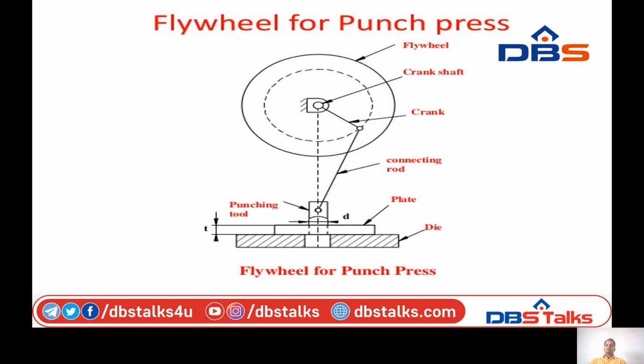We know the function of a flywheel, or its application in an engine, is to reduce the fluctuation of speed. When the load on the crankshaft is maintained constant and the input torque varies during the cycle, the flywheel can also be used to perform the same function when the torque is constant and the load varies during the cycle. Such an application is found in a punching press or a riveting machine.